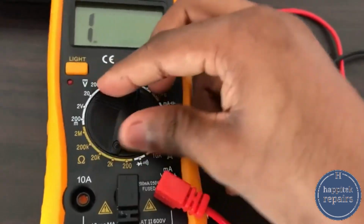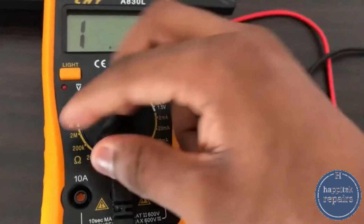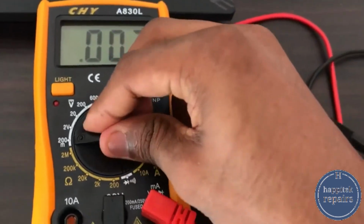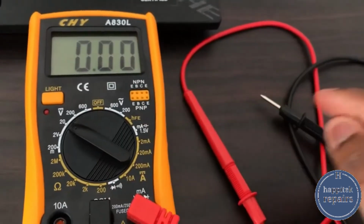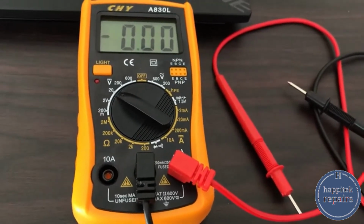You can always set it to 200k if you are not sure, depending on what you are measuring. And here you can measure DC milliampere of 200. There are different ranges we have on a multimeter.